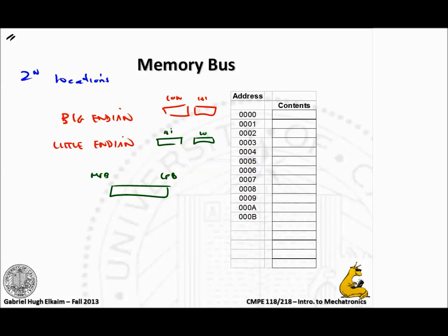So the classic one when you fill memory to figure out what you're doing is you put in hex dead beef. There's a couple of these that sort of spell things you can read. There's dead beef, there's cafe babe, and a few others that are mnemonics. What you generally do is you fill the memory with these, run your program, and then look at the memory again to see how high the stack went. Because you generally have the heap starting from the top, the stack coming up from the bottom, and you want to see if you ever crossed. So you see basically what doesn't read as dead beef or cafe babe.